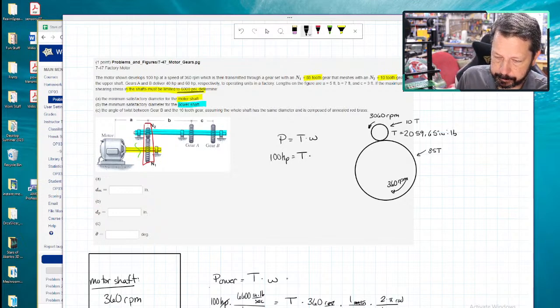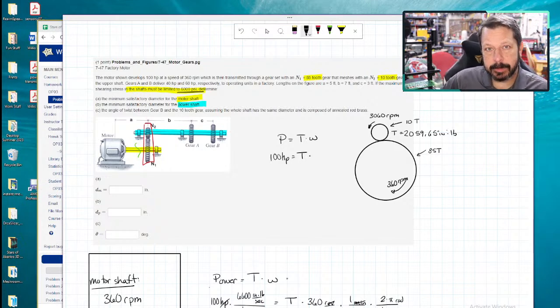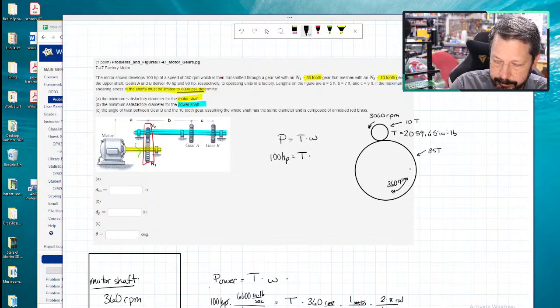And if you did it the other way, where the input gear is the small one and the output gear is the bigger one, then the output gear is not moving very fast, but you're multiplying the torque. If you're relying on intuition and what it looks like, it's probably easier to figure out the speed, because you can envision it. Here's 10 teeth, and I've got 10 teeth on this guy that go all the way around it. Every time 10 teeth of the large gear pass, the smaller one has moved an entire revolution. The larger one has only moved an eighth of a revolution.